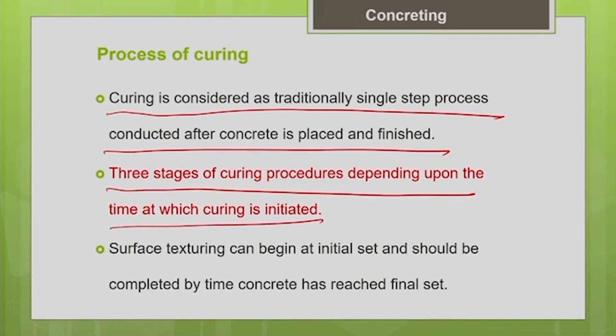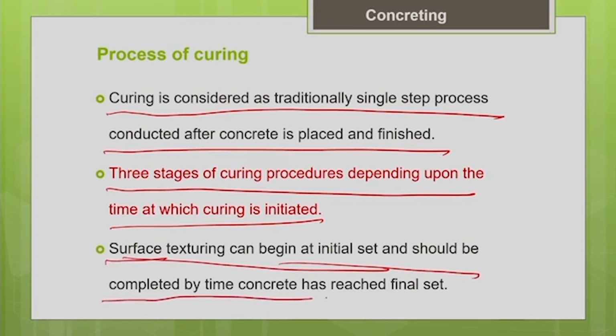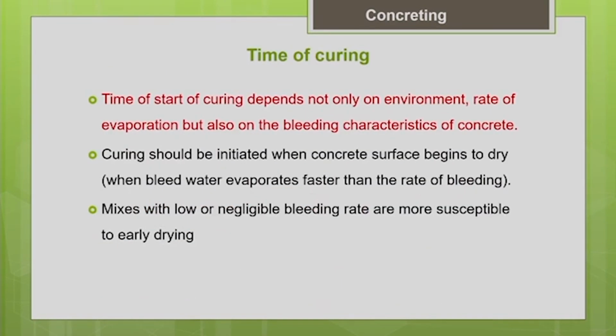So, as we discussed earlier, finishing is done between the initial setting and the final setting. Surface texturing or finishing can begin at the initial set and should be completed by the time the concrete has reached the final set. Now, we will see what time we should start the curing.